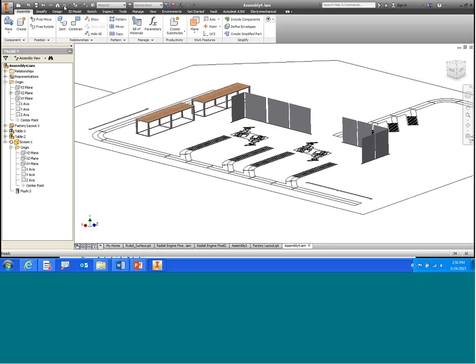And you can see that the tables moved and all the screens got a little bit longer in this one section. So that design change that was made in AutoCAD in terms of the layout reflected in the model geometry that I created, as well as the assembly constraints that I did to place those tables. So definitely some really great applications here in terms of doing your layouts.